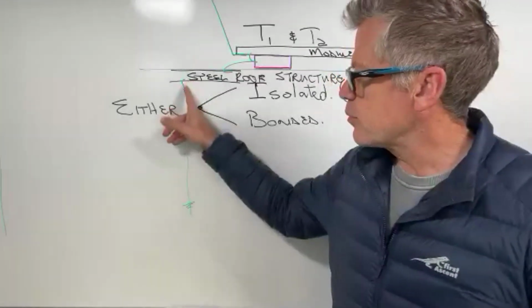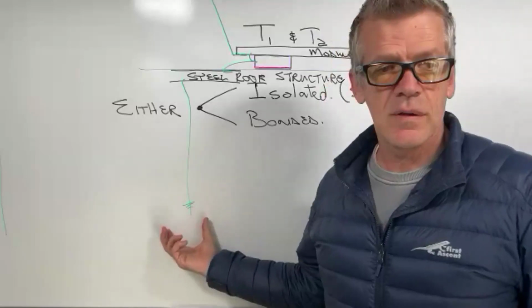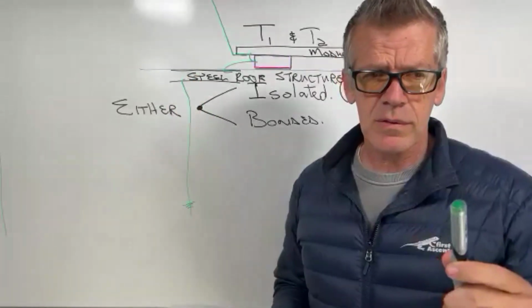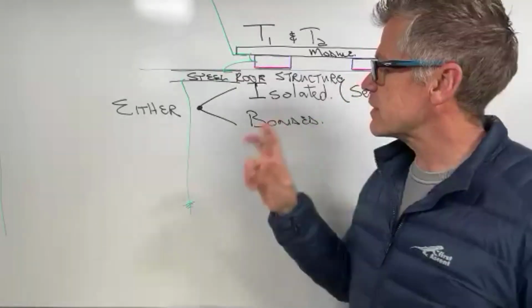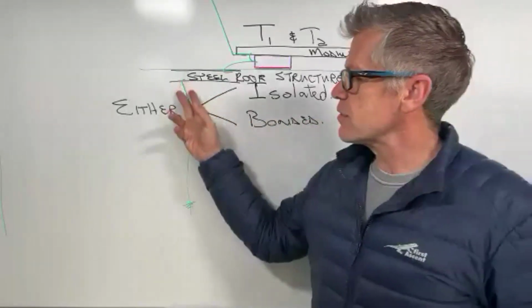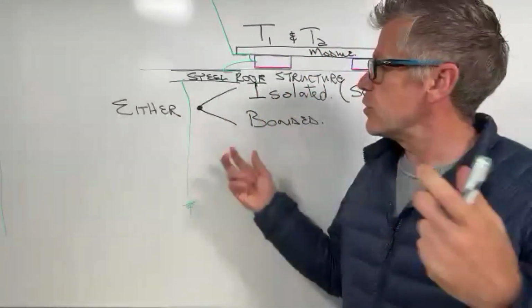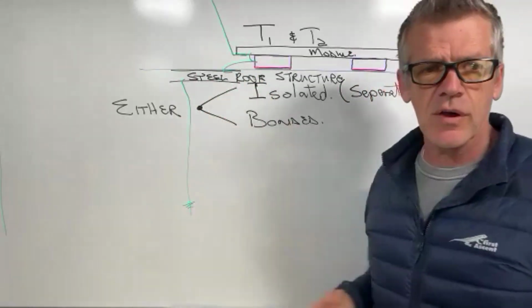If you have steel beams going down and they are bolted into concrete pillars or concrete foundations, this is going to give you a path, and you're allowed to use it according to the standard, but it's not going to help you if you just have one. So the idea would be to ensure when you do the installation that you have multiple paths going down to ground.